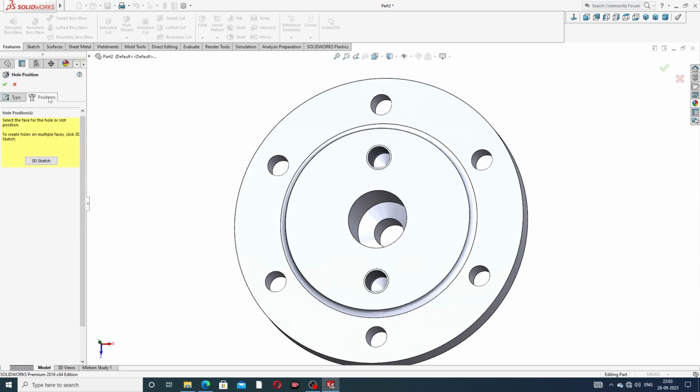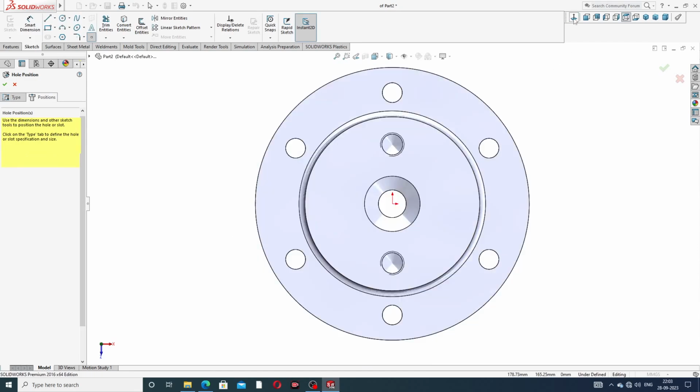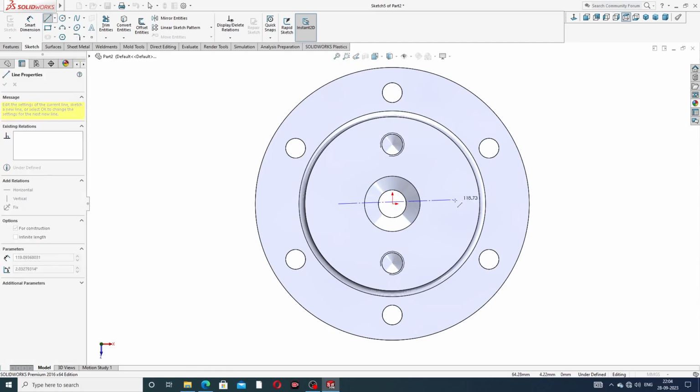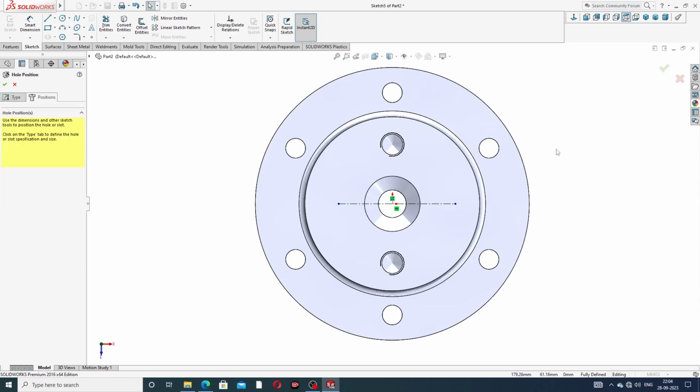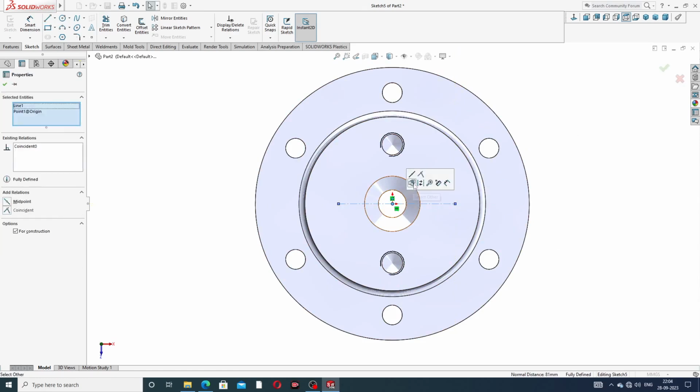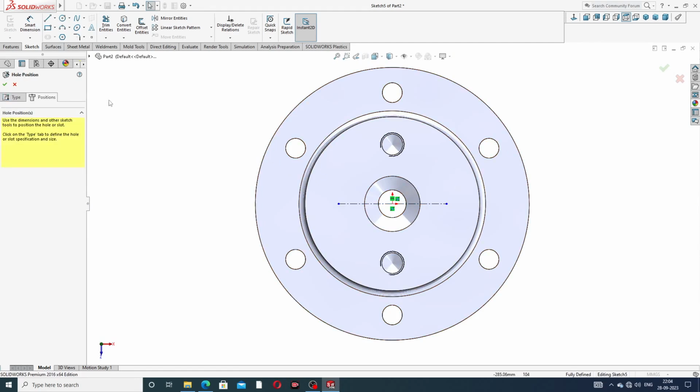And going to option, select this and the normal. Okay, and going to a reference line, drawing here to this, and on this line I press the Control button and select this point, and this is a mid plane, and the dimension is 88 millimeter, which is perfect.